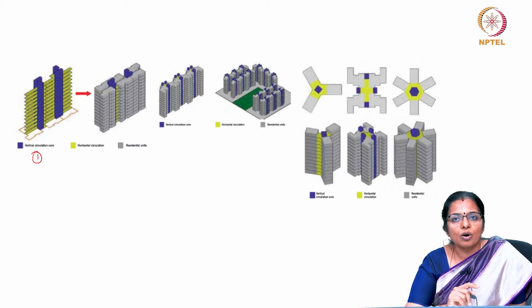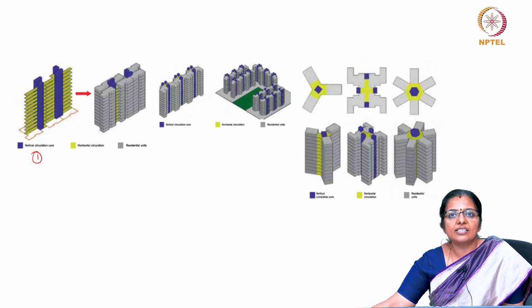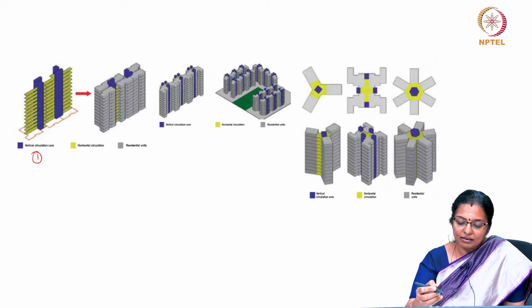Adjoining houses, row houses and group arrangements, all continuous along the east-west axis, which tend to create a volumetric effect, are advantageous, as are the high masses of the building. So, you need to look at various other things, like how you design for various climate types and what your constraint is. So, if you look at hot dry climate, you must have compact and massive design.